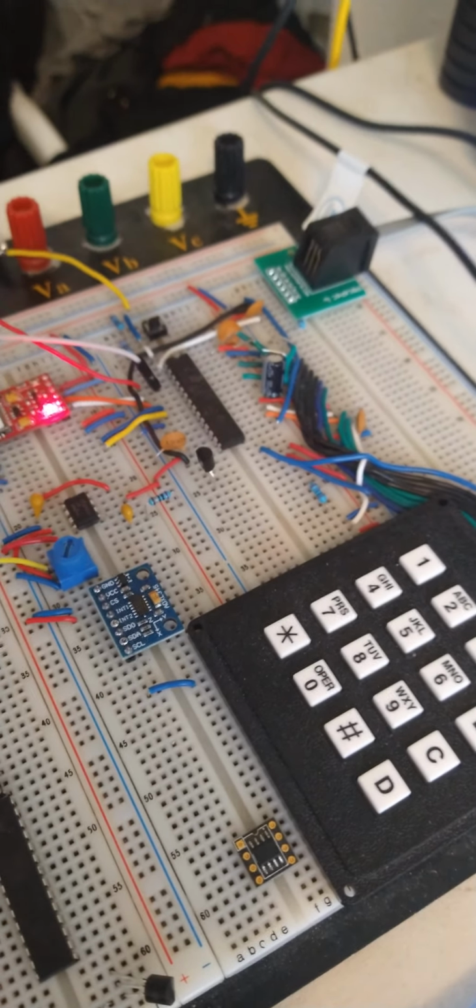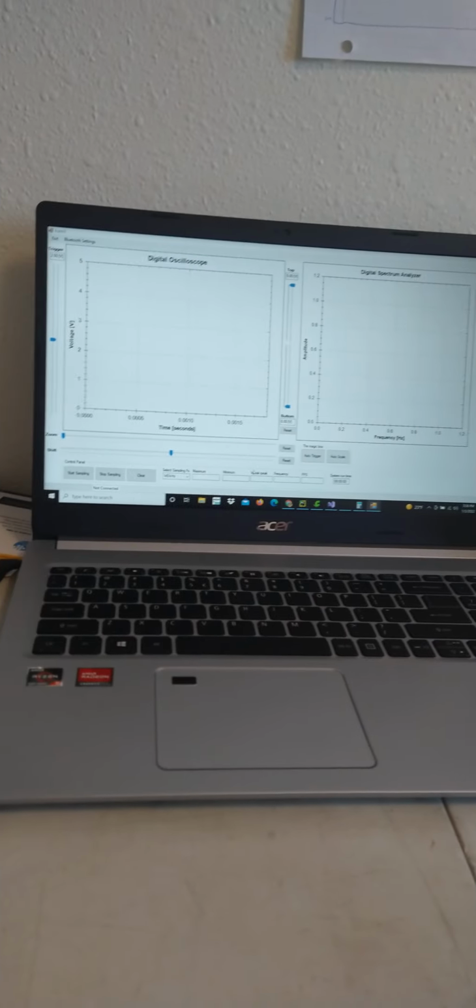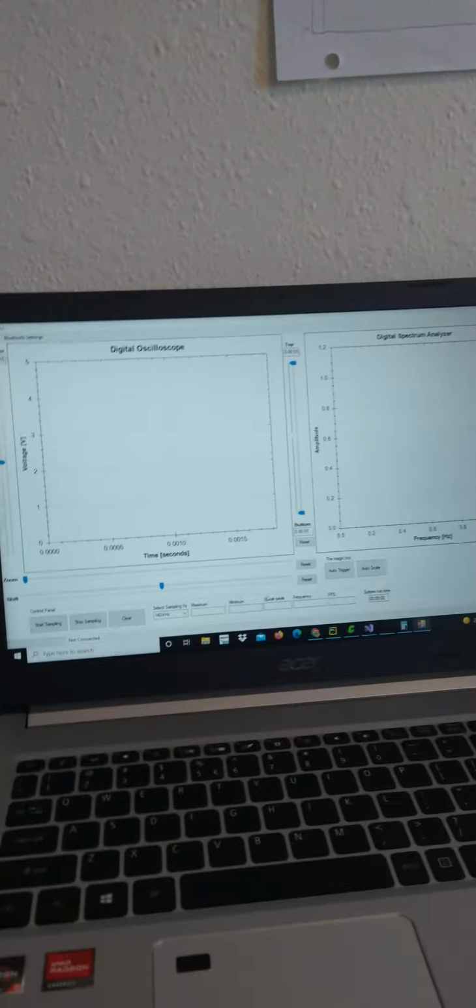At the request for data by the C# GUI application here, PIC24 will gather a portion of its sample data and send it to this GUI application for display so that the user can visually analyze the data. And it does that by communicating with a Bluetooth module here, the RN42. It's communicating with the Bluetooth module using the UART protocol at a baud rate of 115 kilobits per second.